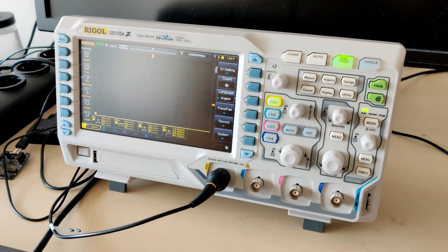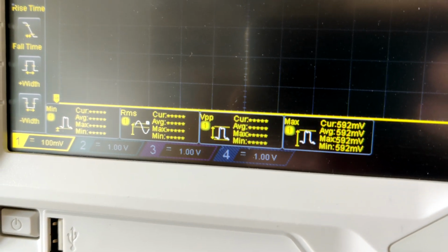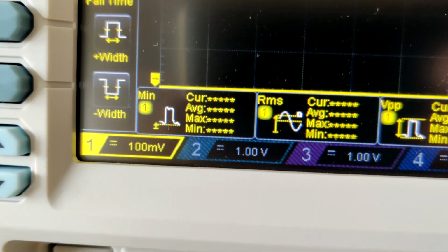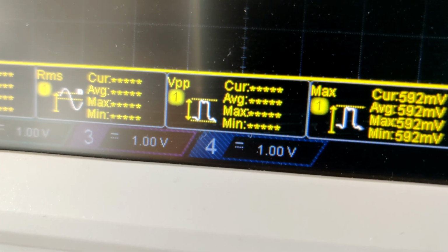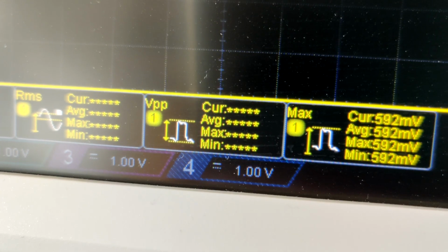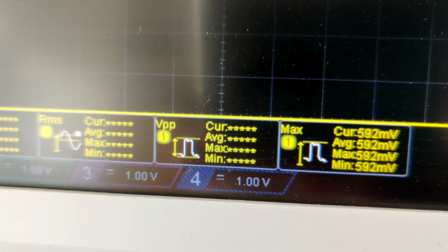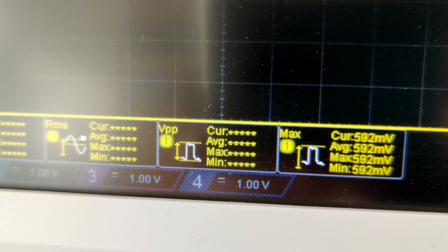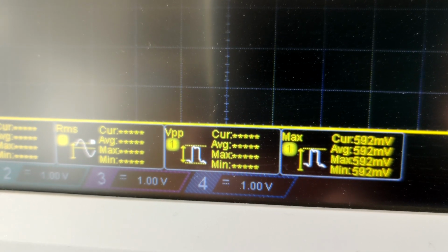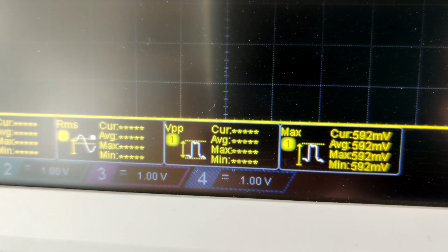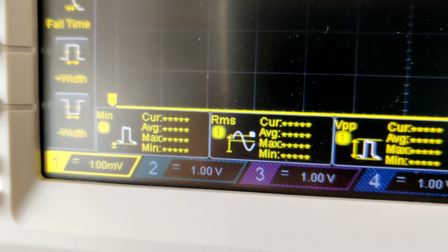So right now you can't really see much on screen. You can just see an empty graph, nothing's really happening. And you can also see empty measurements, but these are the measurements that we can see. Here's the minimum voltage that I talked about. RMS is the average, and our maximums are our maximums. And then VPP, you can probably guess from the image. VPP is the difference in voltage between the maximum and the minimum, which is a general measurement of how good your VRM regulation is, but it's not an absolute one, because you can get better VPP by reducing your maximums, which does nothing for your overclocking, but it does reduce VPP. So don't take it for an absolute value, but it is a pretty good general indicator of how much your voltage swings around. But really the important bit is the difference between the minimums and the RMS, or average, as I've called it before in the theory section.